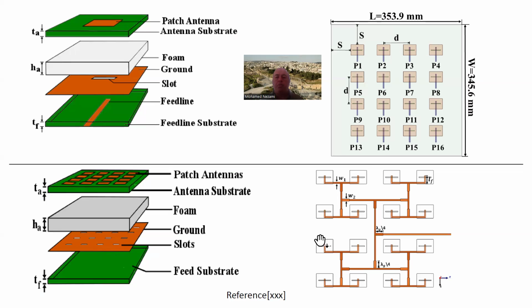Now the feed, of course, you design like this, and we went through these designs in the last video, number 2 of this series. I showed the principle of designing the feed network using T-junctions like it is shown in here. And we focused on the tapered feed designs. In this one here, you can see that the transmission lines are all equal width, meaning they're all equal impedances, except the transformers, of course. So at the feed point to the element, all the lines are the same width. This means that this is a uniformly fed, uniformly illuminated antenna array, in which the side lobe is at best minus 13 dB below the maximum gain, or the maximum directivity.